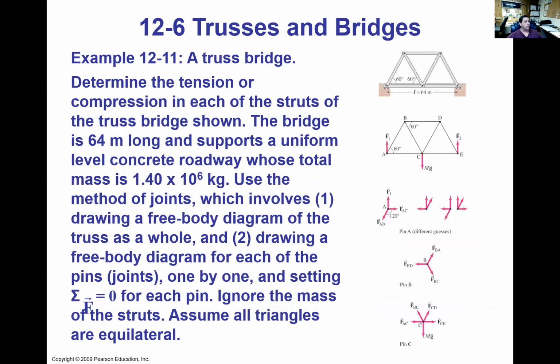Right, so you can go through and do free body diagrams and solve for each of the components of that using just simple equations of equilibrium. Sum of forces, sum of torques, all equal to 0. Do it at each of those pins, at each of those locations, and you can figure out what each of the components of that bridge are experiencing.